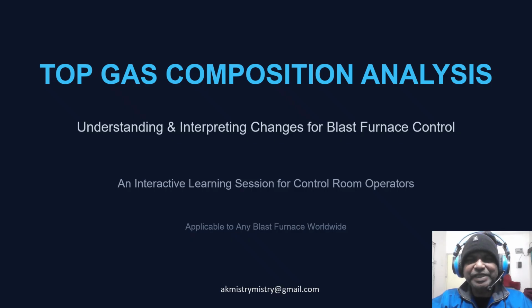You will also see the reaction products carbon dioxide and water vapor, plus small quantities of oxygen and methane. The key point is that top gas composition acts like a live indicator of the reactions happening inside the furnace, giving the operator a continuous picture of process health.